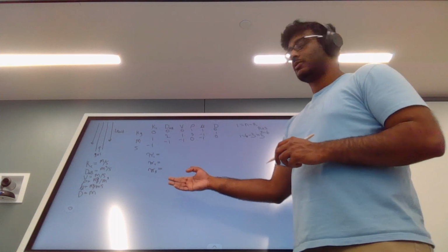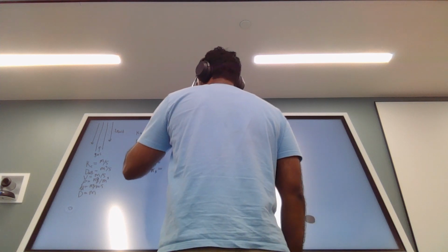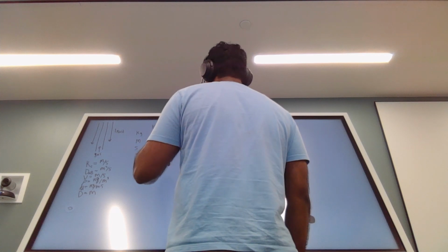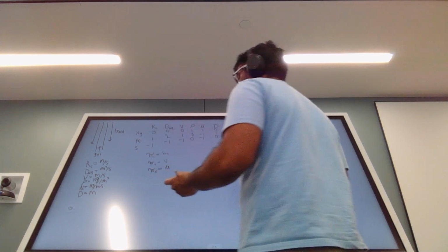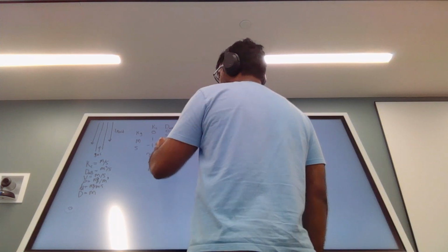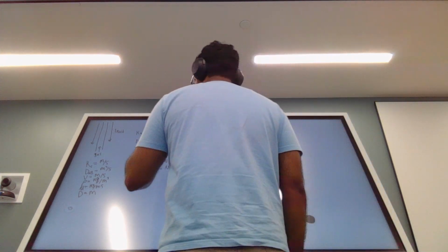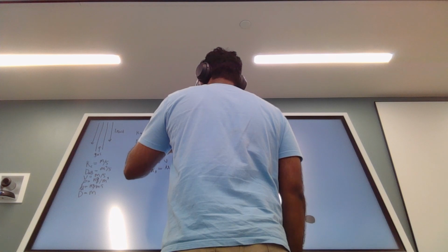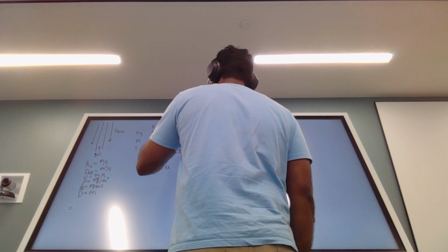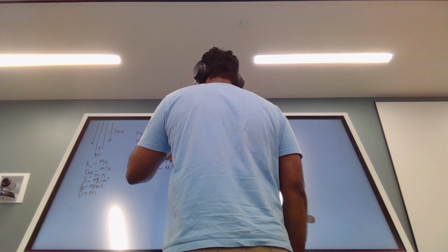So now what we're going to do here is go ahead and write the variables we want to isolate. So kc for pi 1, velocity for pi 2, and viscosity for pi 3. And we're going to go ahead and fill in the rest of the equation with the other 3 variables that are not isolated. So the other 3 variables are going to be DAB, density, and diameter. And we're going to do that for all 3 equations.